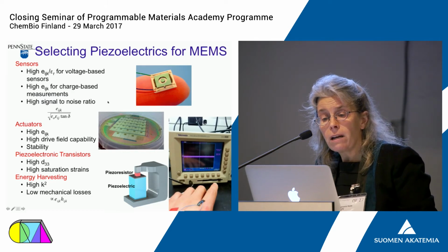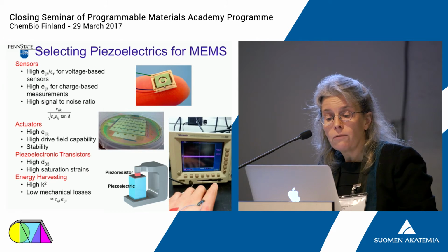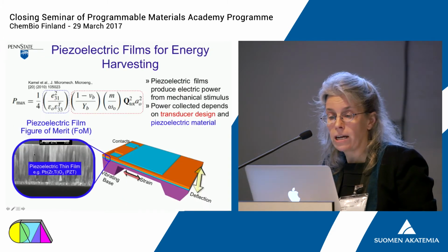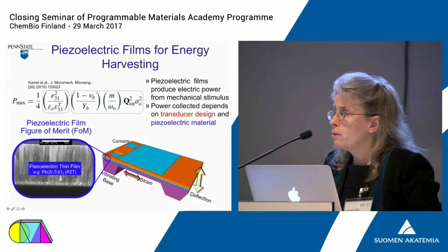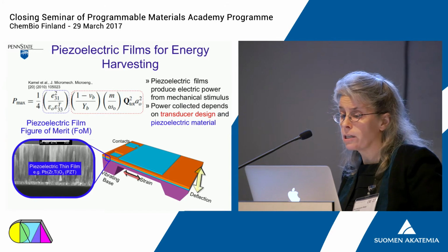The key figure of merit for the sensor application is the piezoelectric e31 coefficient divided by the permittivity. For energy harvesting, the key figure of merit is that piezoelectric coefficient, the charge coefficient times the voltage coefficient. And I'll come back and talk about actuators in a moment. But let's think first about this mechanical energy harvesting application.